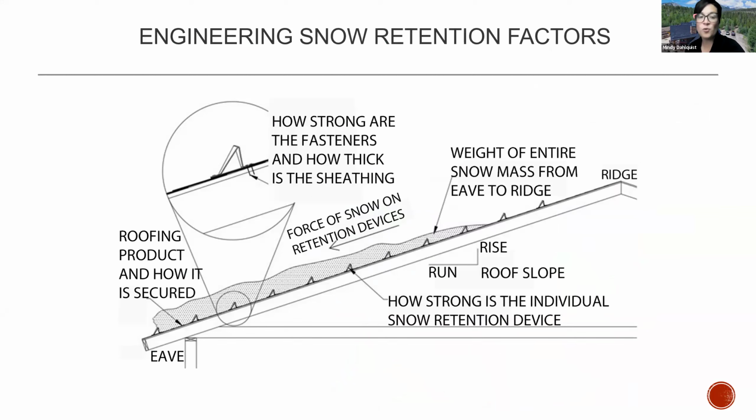What is the force of the snow on the snow retention devices? What is the weight of the entire snow mass from eave to ridge? What is your roof slope? And how strong is that individual snow retention device? Some of this information you can look up, or your roofer can look up.